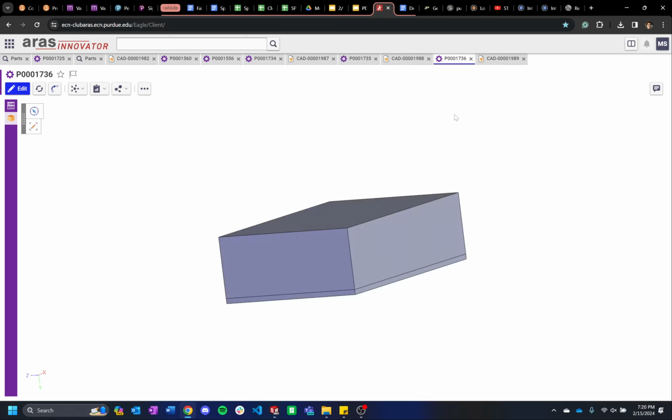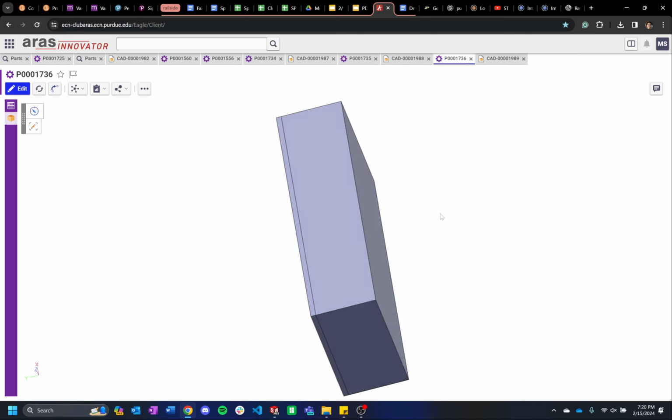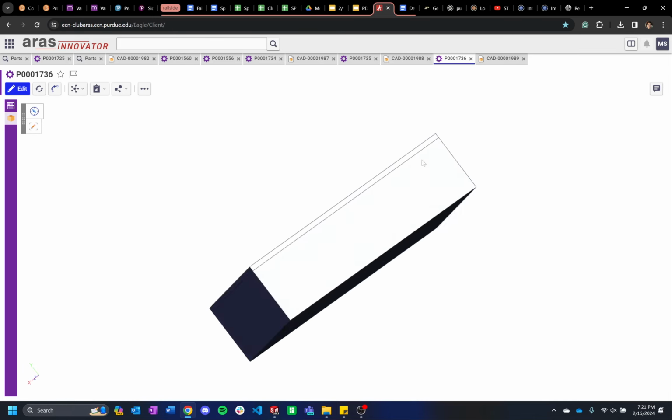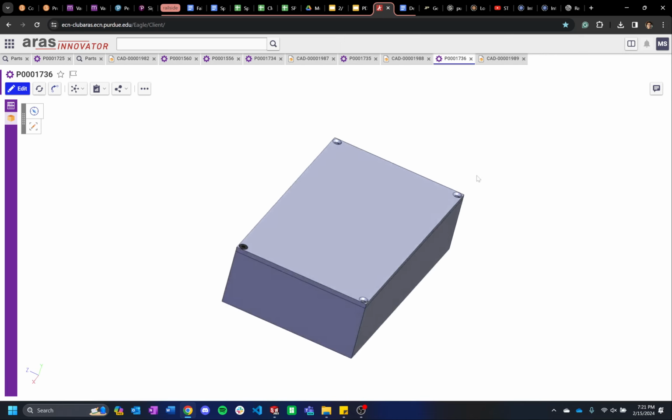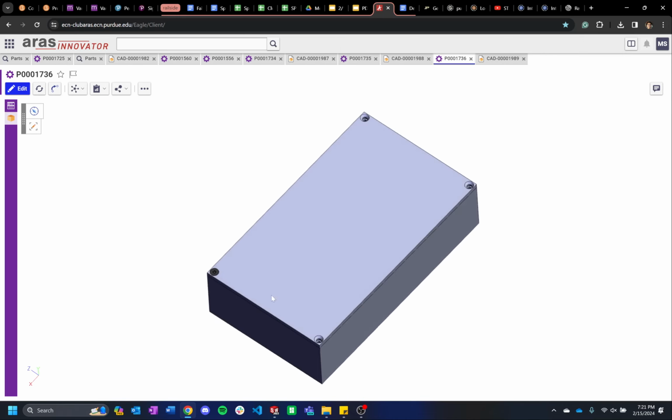Aras is able to understand that. If you upload all your files and you look at it in the 3D viewer and a component's missing or it just doesn't load, that probably means you didn't link the CAD documents correctly or to the right documents somewhere along in that process. So you should always check after you upload everything on the part in the 3D viewer just to make sure that everything goes together. But once you've done this, you've finished your assembly, it's done and complete.